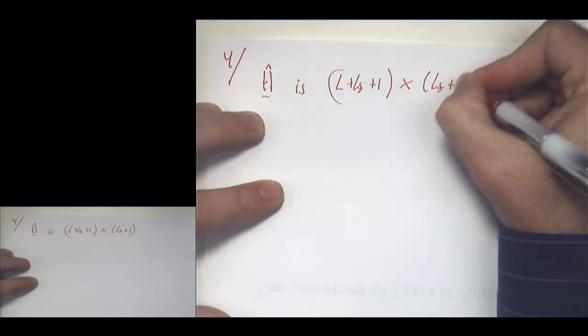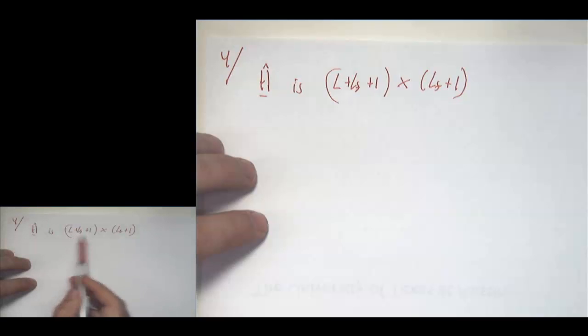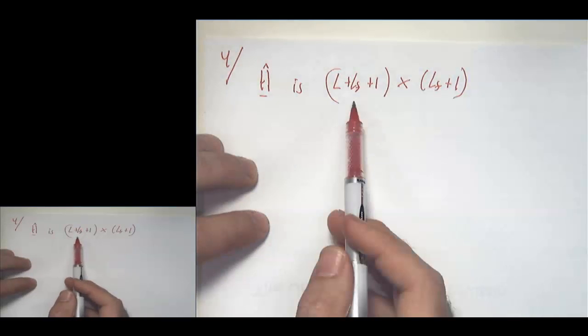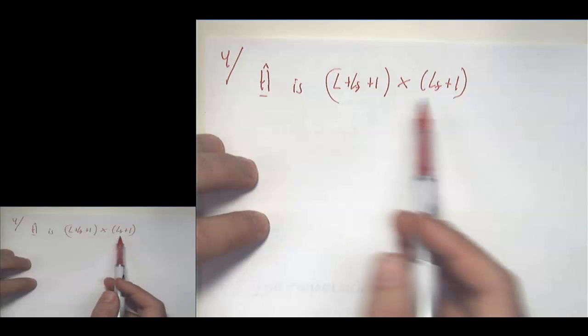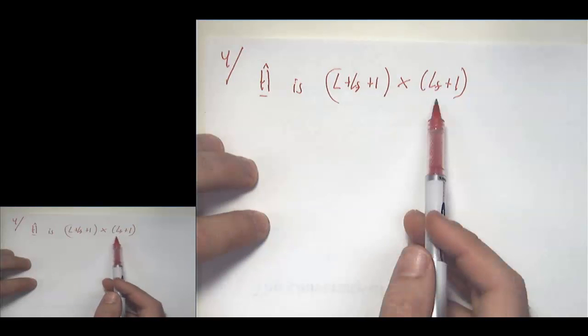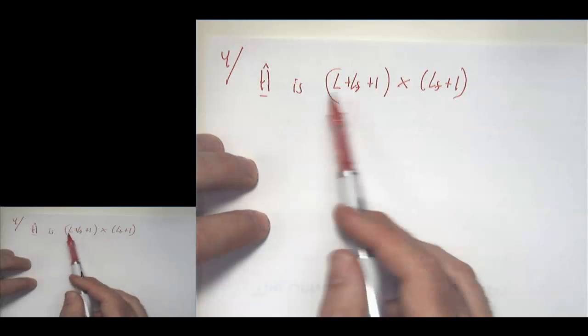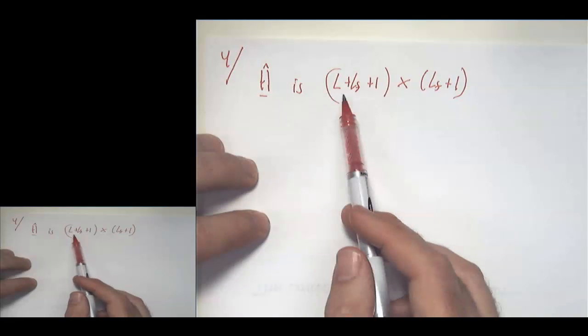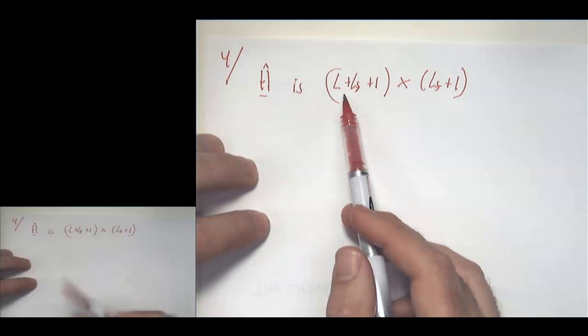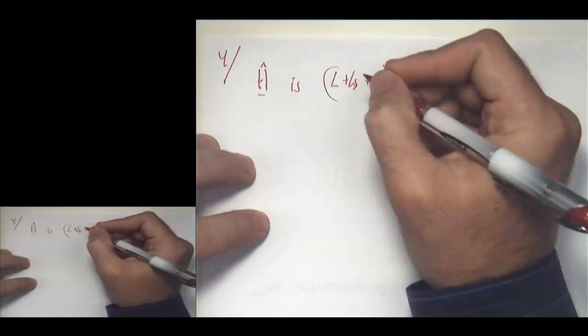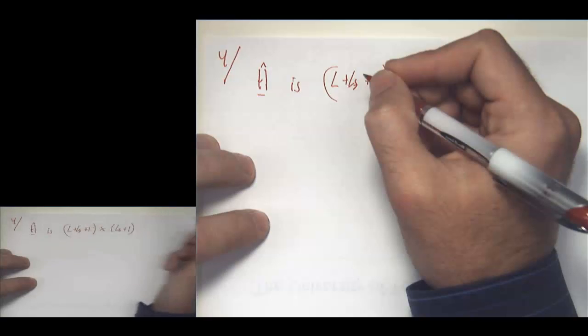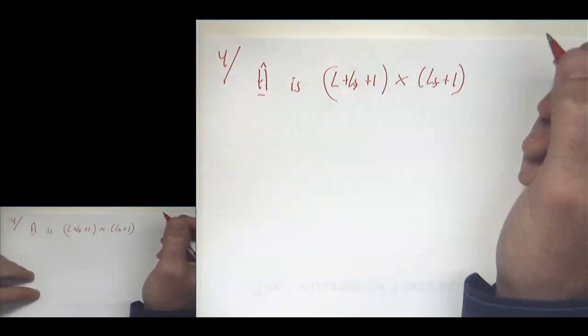This makes sense because the output of the convolution is, as I mentioned before, the sum of the lengths minus 1. And then this is the unknowns here. So this thing is always tall, unless L is equal to 0. There's no exact solution possible unless L is 0, but then that's the flat fading case, which is boring.